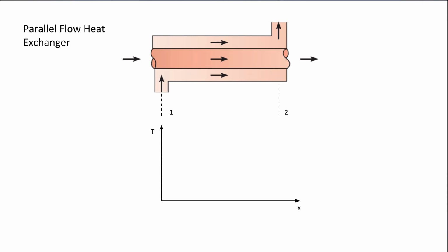Let's say, in this case, it doesn't matter which is hot and which is cold. I'm going to make the temperature profile for the hot fluid, meaning temperature of the fluid versus length into the heat exchanger. What does this curve look like? Is it flat, up, or down? Down. Okay, thank you. Now, if the hot fluid goes up, that means the hot fluid is getting hotter, right? There is your Nobel Prize, right there, violating the second law of thermodynamics, right? The hot fluid gives heat away, it doesn't get heat.